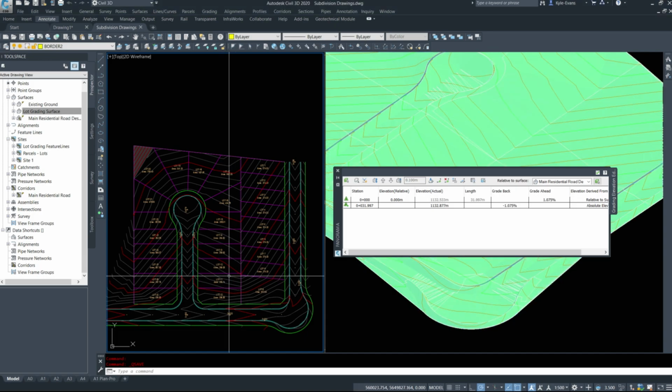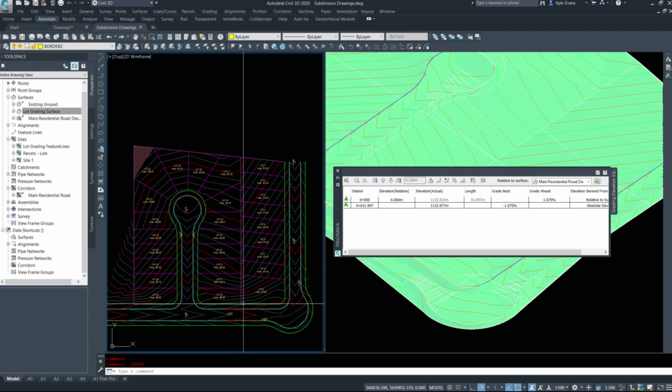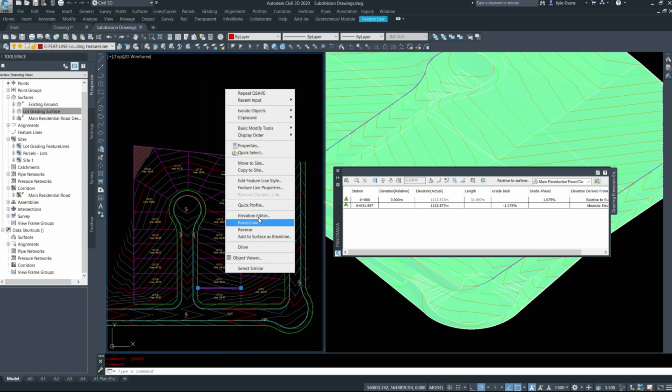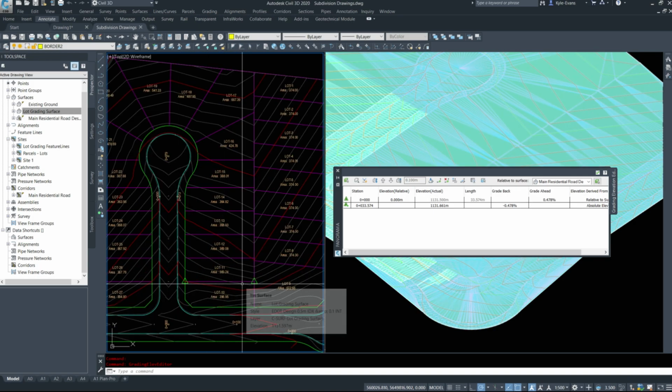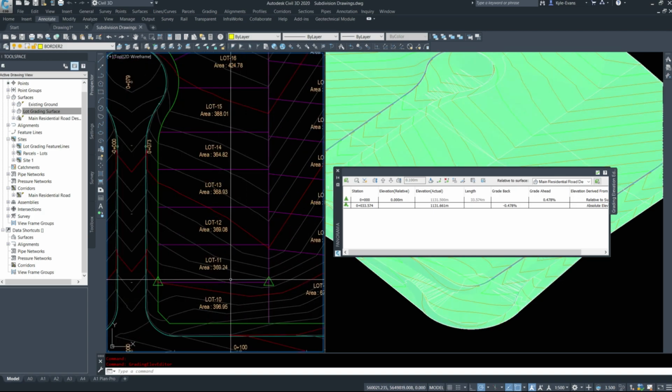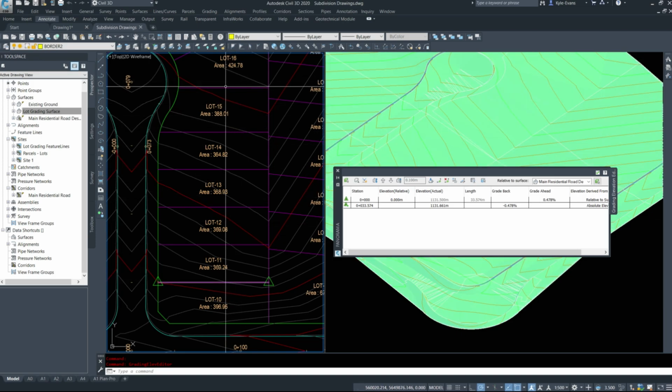Alright, I've gone and made all those feature lines 2% up, and I've matched these elevations in. However, if we look at the elevation editor, we are now at a slope of 0.478, which is less than the minimum slope within the city of Calgary. So we need to make these lots split. That means half the lot slopes up, half the lot slopes down, or we might adjust the high point to be near the back. Actually, let's do it in the dead center.